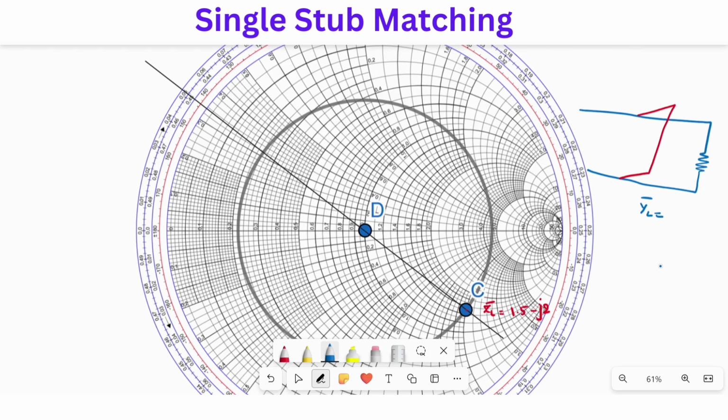As you can see, this is your VSWR circle that we have drawn just now, taking the midpoint as center and your load point as radius. Using the compass, we have drawn this circle, and we have to extend the line that is joining the center and the load towards the opposite side. This straight line will intersect your VSWR circle at a particular point. As you can see, it is intersecting right here. So this point will be our YL bar, the normalized load admittance.